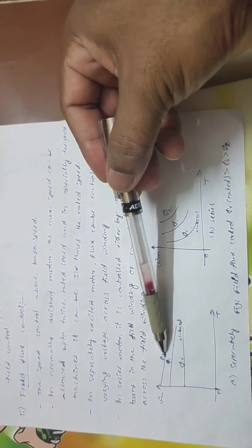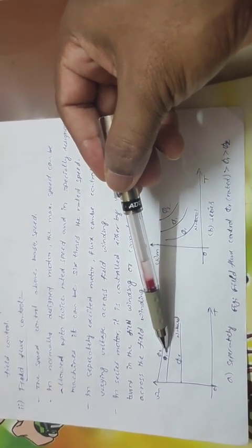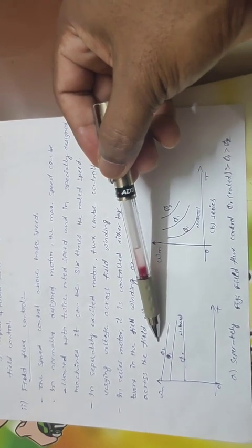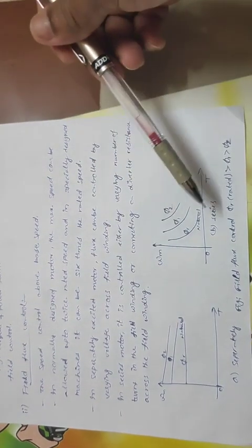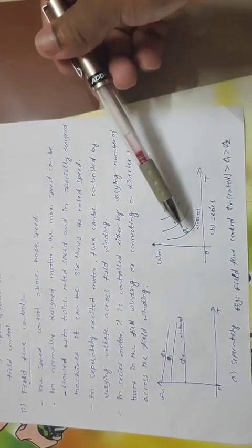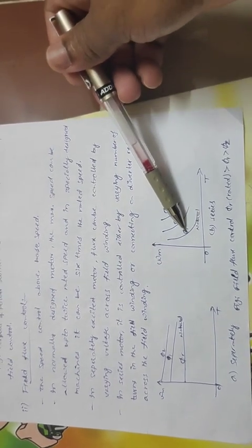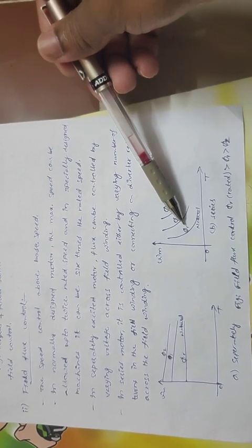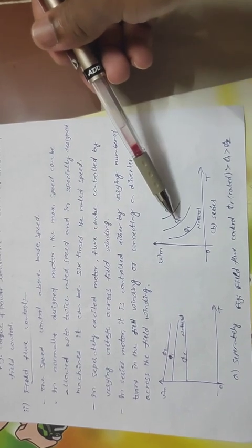Here phi 1 is less than phi r, and phi 2 is further less than phi r as well as phi 1. That's why the characteristics shift upward, that is above the base speed. In a similar way for the series motor, these are the natural characteristics with rated flux phi r, and when you are decreasing the flux, phi 1 is less than phi r, phi 2 is less than phi r as well as phi 1.